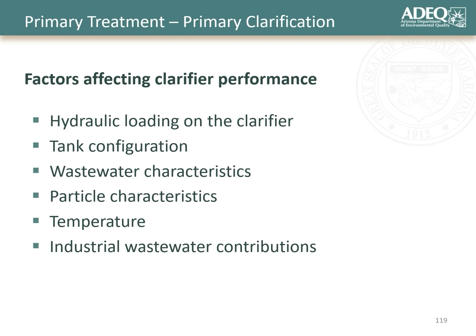Number three, wastewater characteristics, which can include particle characteristics as well. If you happen to have a wastewater stream with organics that don't settle well, they're not going to be removed in your clarifier, so you get poor performance related to that. Temperature, of course: as temperature decreases, the density of water increases, which means that your particle needs to be denser to be captured. Otherwise, it's going to float. That can have a potential impact on your clarification performance.